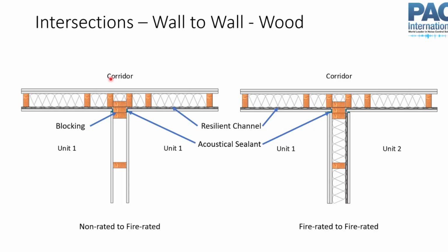So we want to make sure that we go trace, do we have a continuous mass layer here? So in this case, we've got this drywall that goes all the way across, and here we have the wood, we've got sealant here, and that's continuous all the way across. Obviously, this is continuous all the way across. Now, we don't care about sound isolation between these two that much, right? At least it's not a code requirement for isolation between bedrooms or bedroom and bathroom within the same unit. So this structural path, all this is okay. But we want to look at, are there rigid paths here?